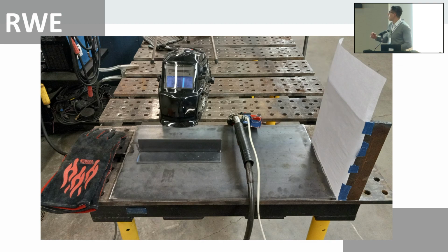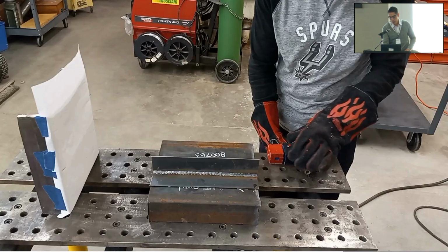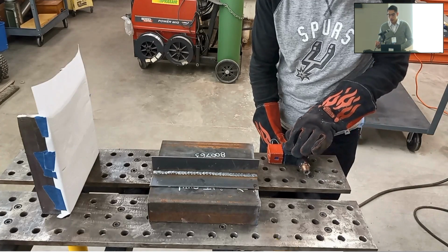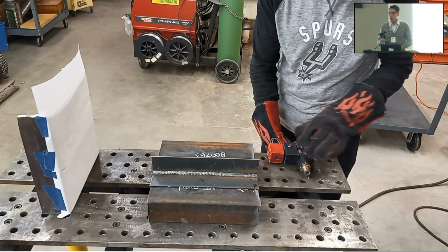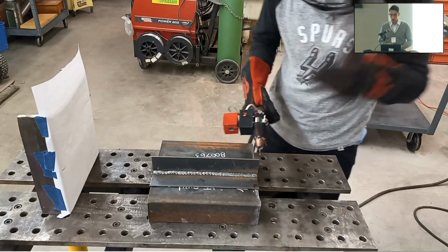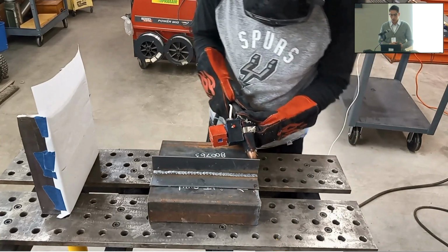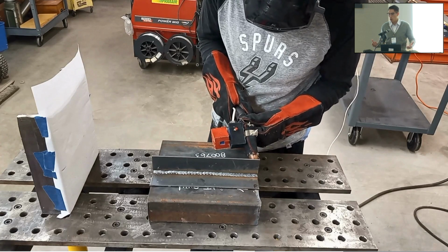On the left part, we have a reference that helps the distance sensors measure the displacement and the speed. You just need to attach it to your weld torch. You press the set button, and it sets the zero and begins collecting data. And you just begin welding, basically.